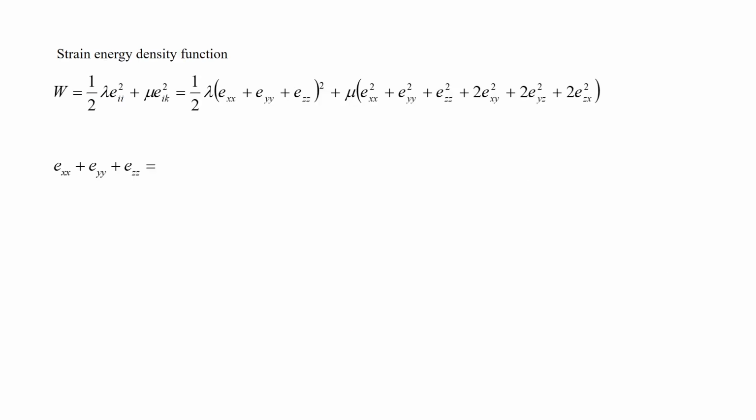And so therefore we can actually estimate what will be the strain energy density function. So remember that this particular expression I have given in lecture 3 or lecture 4, okay, where the expression of lambda was also given, mu is the shear modulus. So this is the Lamè's constant. So now Exx plus Eyy plus Ezz, and then you have to estimate this quantity. So we will like to do that.